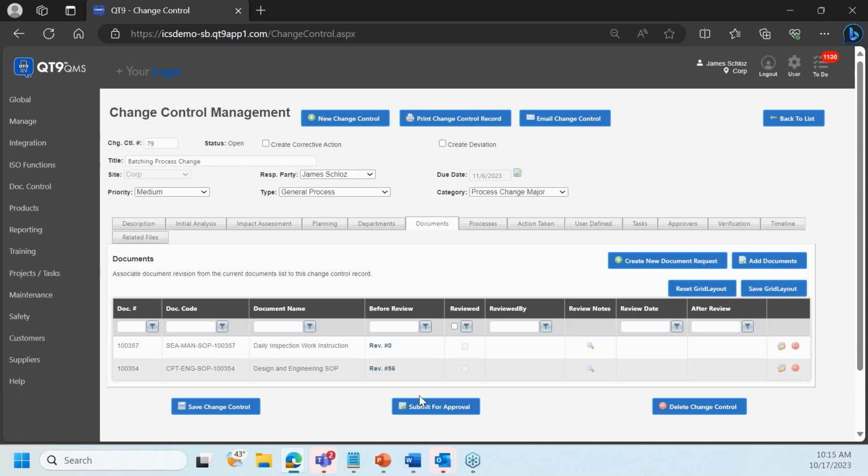All right, so when we talk about this, it is different, obviously, than ECR and ECN. Now, one of the biggest differences between ECR, ECN, and change control is that an ECR and ECN is two modules, so it's broken down into two components. So we talked about this, that the ECR is used to approve the potential changes, where an ECN is to document that change.